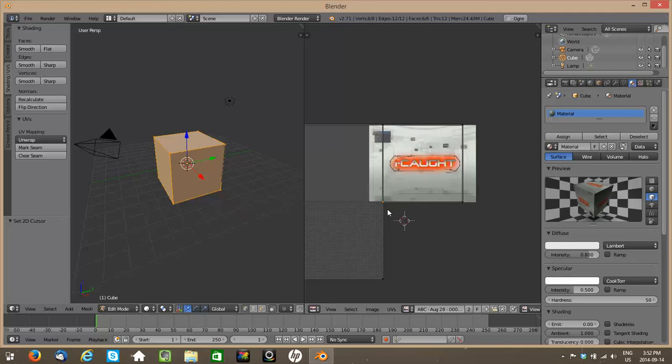The vertex that I've selected is still selected. I hit G, and I get to pull this UV point completely out of position from where it's supposed to be, just to prove that there was actually more than one position there. But it's by doing this repeatedly that we would UV map the entire object. So this object has a total of 8 vertices.